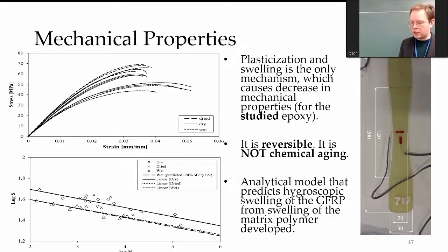It can affect the speed. In this case, we didn't look into that. However, more interestingly, it affects the fibers more than the polymers. For example, with glass fiber, the aging will be very strongly affected by pH and salt. Usually going to the wind turbine industry and blades, which were glass fiber composites.